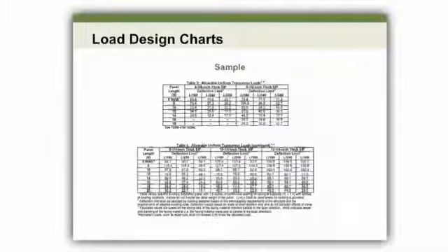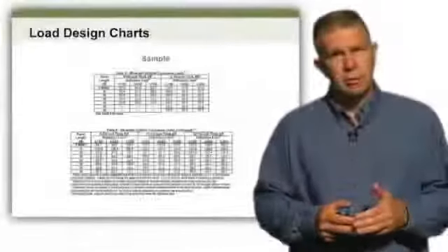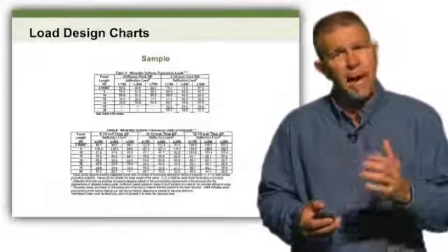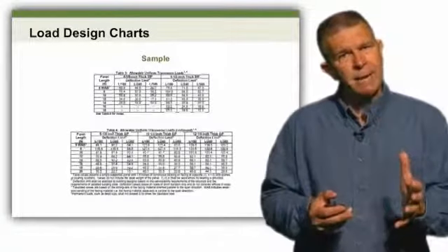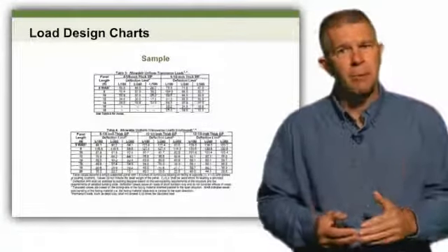And it's these load design charts that give the basic information that architects, designers, and engineers utilize in making the design decisions to determine how the panels are going to be joined, the thicknesses of panels that are going to be used, how far the panels can span. And it's beneficial for you to understand that these load design charts are not only available, but how to use them and know when you're asking a panel to do something beyond its capabilities.